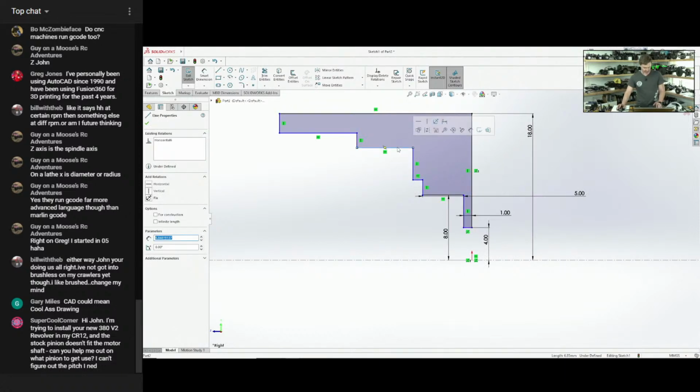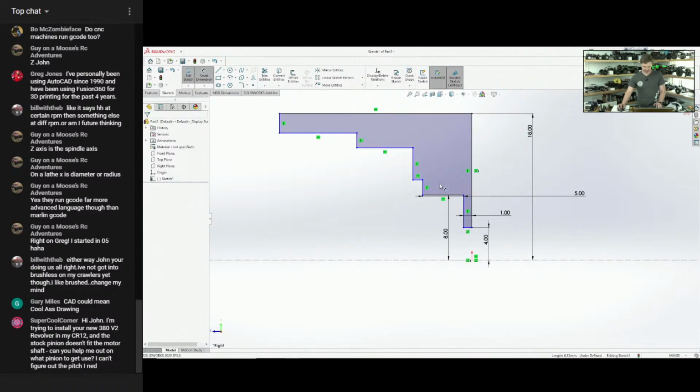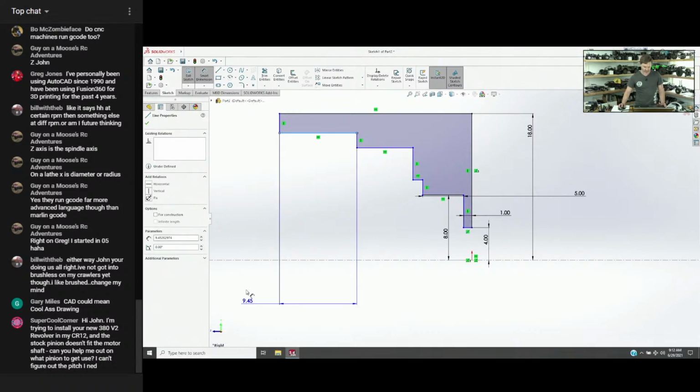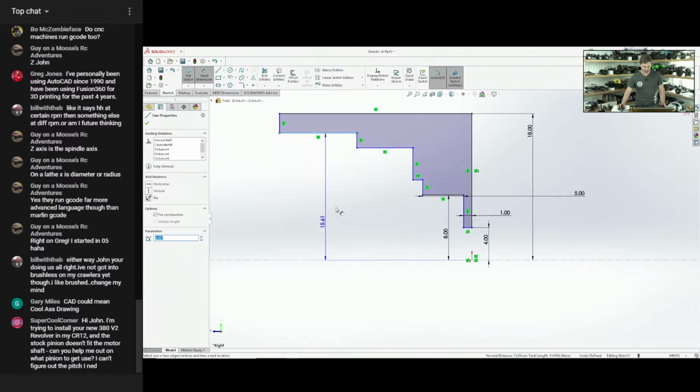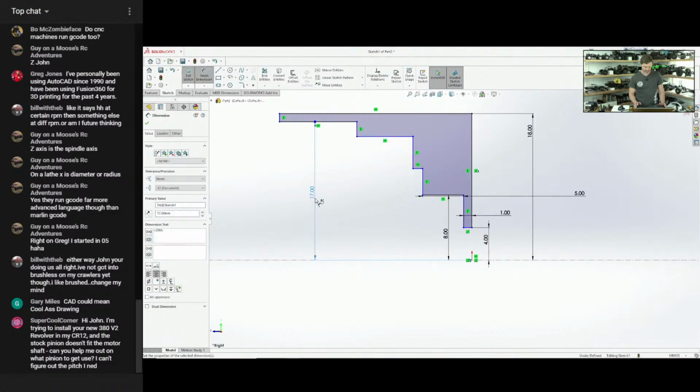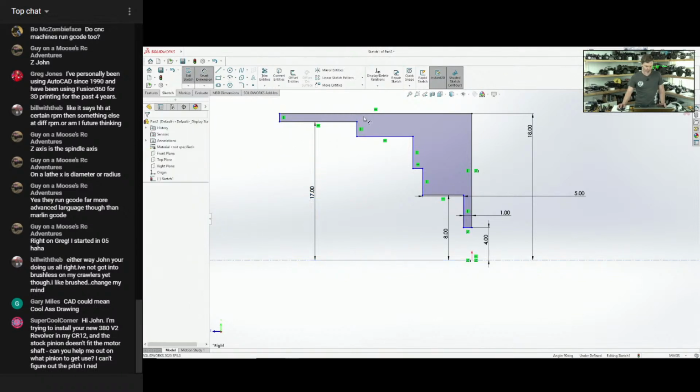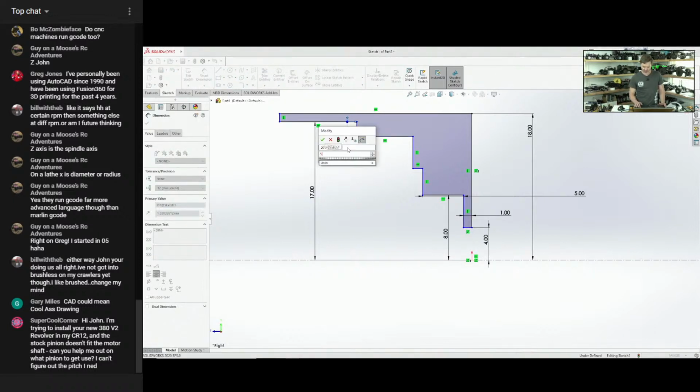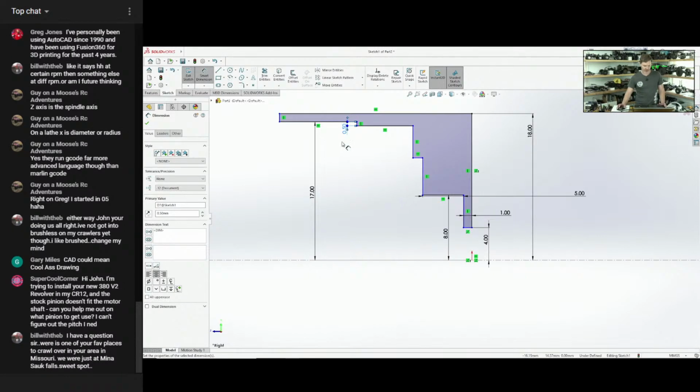So I know how much clearance that I need personally. This is stuff that if you don't have all your bits in front of you to measure, then it's kind of hard to figure out. But let's see. All right, so this guy, one step at a time. I know that my stator needs a 17 millimeter radius, and these are all nominals. Something that I definitely should mention is that when this goes to a machinist, you can send them a drawing and they're going to machine really whatever they feel like machining if you don't have your tolerances on here.